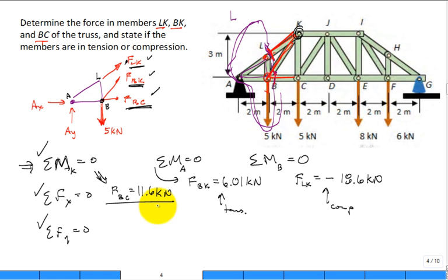All right. Yes? Okay, yes, you're right. I skipped that point. Okay, do a global system. If you do the sum of the moments around G for the entire truss, you'll have just AX and AY. If you look at it, we only have vertical loads. So what is AX going to be equal to? AX will be 0 because of the global truss.